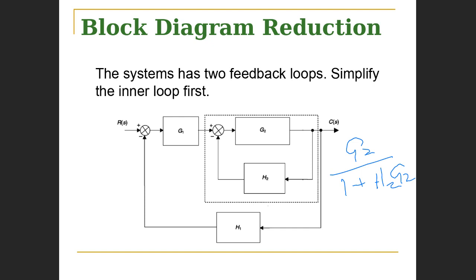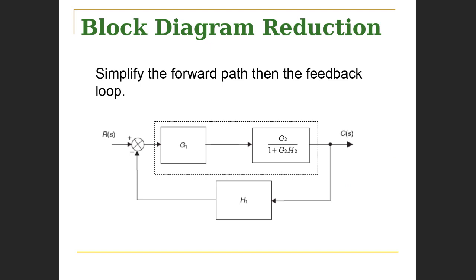All right, so let's go to the next slide and we're going to see the result. That is in fact the correct representation. So I hope that we're seeing how we apply this rule. We need to simplify a feedback loop. We have to apply the appropriate feedback loop reduction rule. Now, I'm highlighting this section that we're going to seek to simplify. Reason being, we couldn't apply directly the feedback loop here because we have two blocks in series. Are we seeing that? We have two blocks in series here, and so we have to take care of that part first.